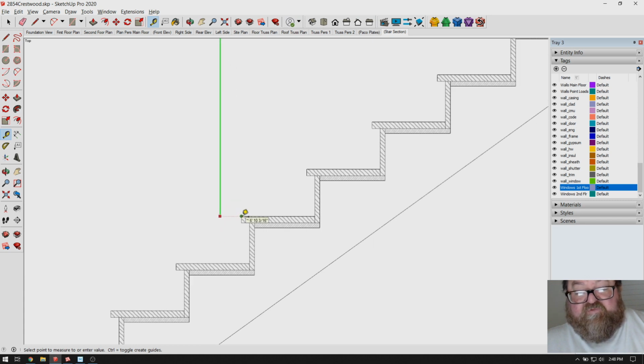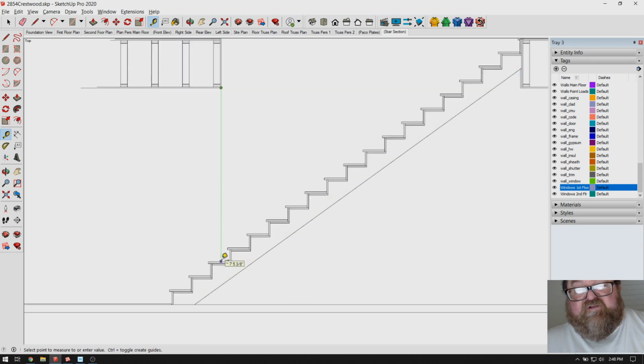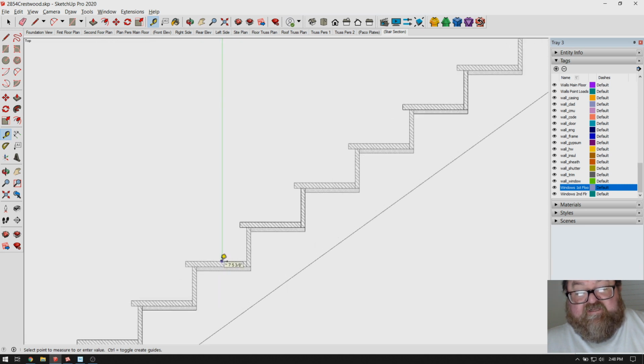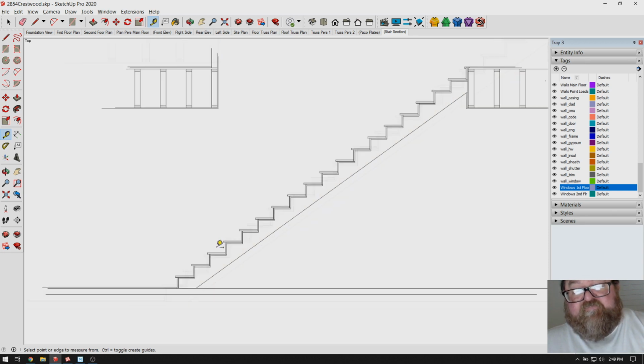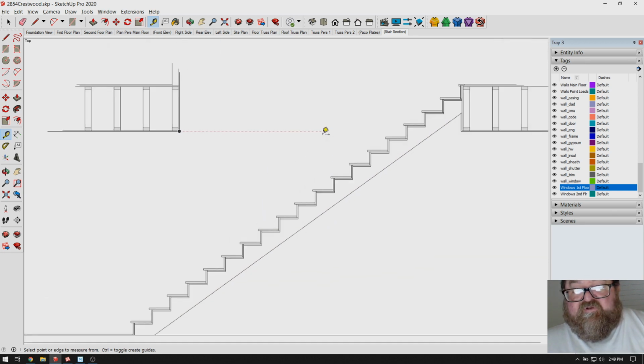Make sure, if the building inspector is in one of those moods and he says, no, I want this one to be 6'8", because I would claim my head height is 7'5", they're supposed to measure directly down to the step that hits, okay? But I always make sure the next one is at least 6'8", and I've got 6'10", so we're good, okay? Those are the important aspects of this.